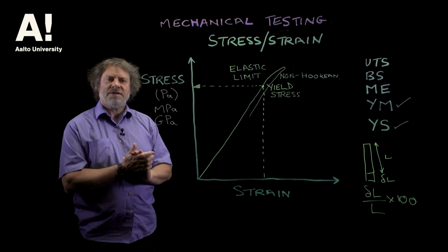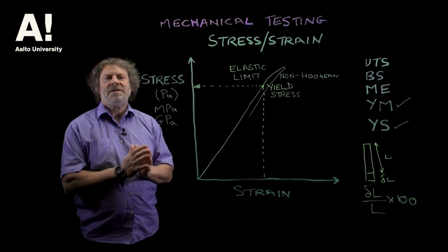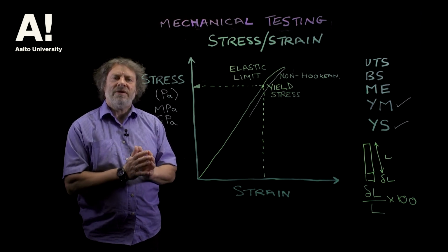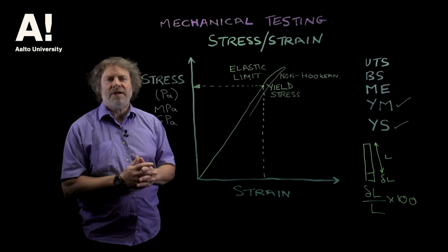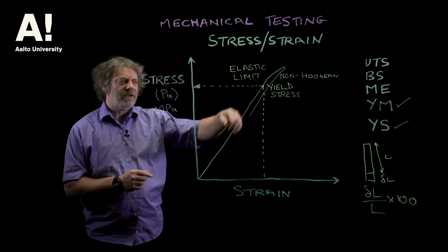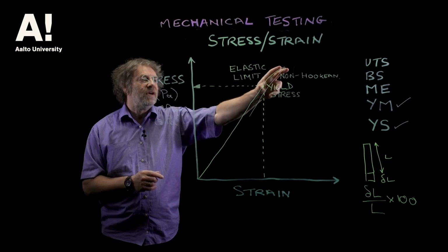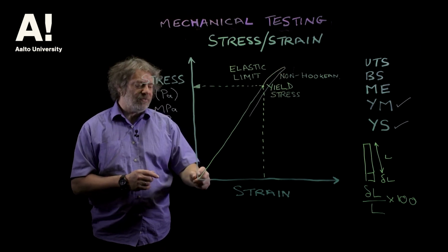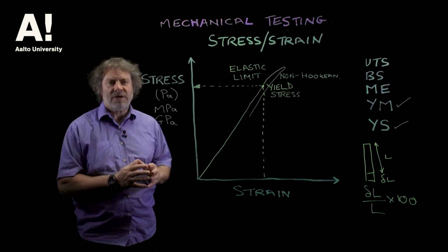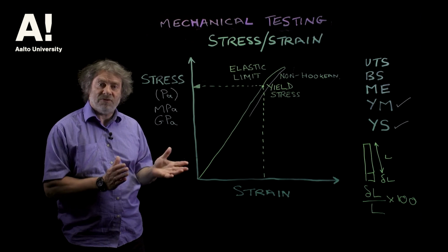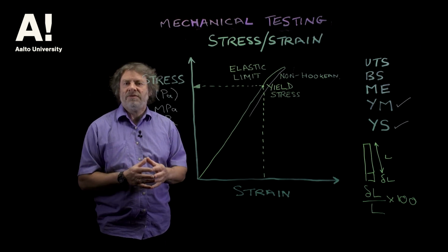I talked about this elsewhere when I was talking about the rheology of wood. It's quite complicated and it depends on the time over which you apply the load. So if we do this fairly quickly, if we apply this fairly quickly, we're not going to see this behaviour until quite late on. But if we apply the load very slowly, we're going to see non-Hookean behaviour coming in almost immediately, depending on how quickly we apply the load. So this duration of load thing is really important.